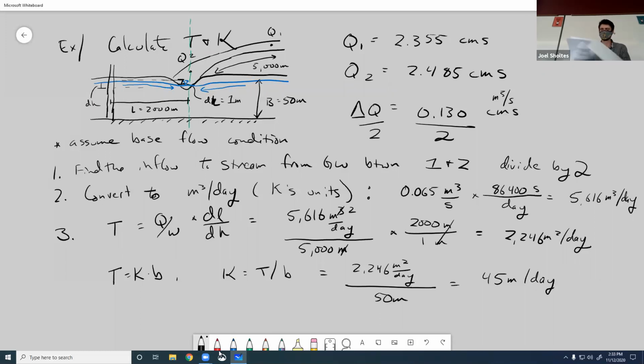Structure like a lower dam, would that be good? We used weirs. You can use weirs to calculate discharge. A dam like that, certainly, you could come up with a weir coefficient for it. So yeah, really any kind of hydraulic control can be used to get a better representation of discharge.